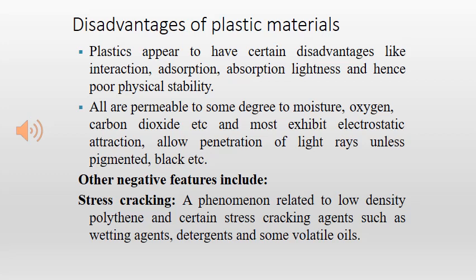Poor impact resistance can be seen in both polystyrene and PVC. They have poor resistance basically. This can be improved by inclusion of impact modifiers such as rubber in case of polystyrene and methyl methacrylate butadiene styrene for PVC.